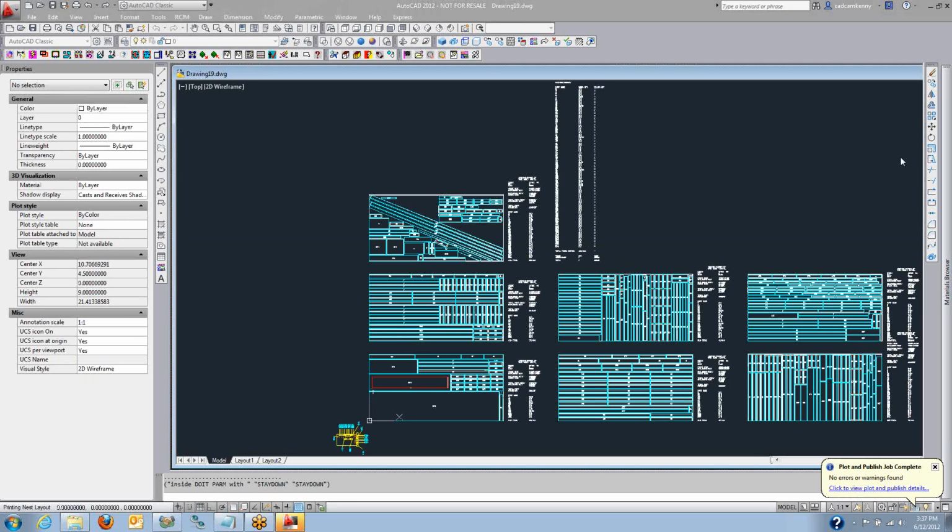Here's some nested parts. Now some of those parts on the diagonal are longer than they'll fit on the sheet horizontal. So you see how the nesting handled that. We're doing a tool stay down nest. So the tool stays down and connects from part to part without lifting up. As you can see in these nest results, we've got some very tight yields, possibly using 100% of the sheet in some cases.